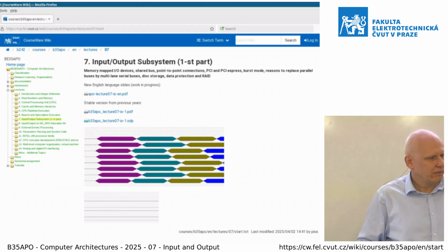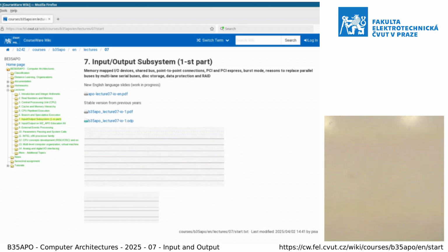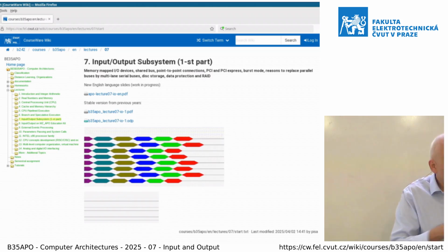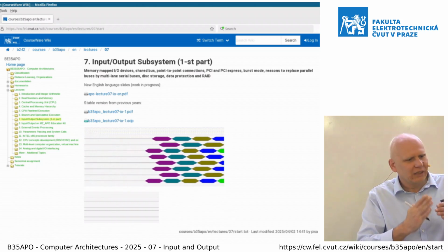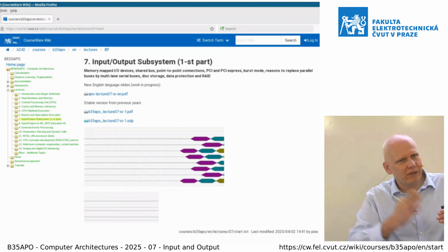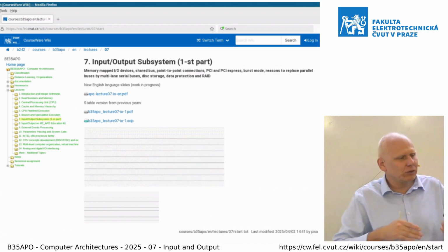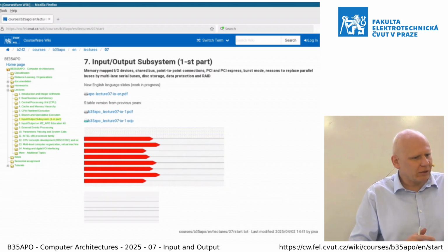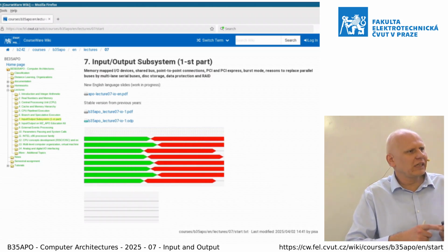That is why, in a parallel bus, all the traces have to have the same length. In this case it is not necessary. In the case of a parallel bus, yes, because you need a match between the clock signal and the data, and the data has to provide the word in the sequence at a single time. But when you switch to serial links, it is no problem, because for each lane you reconstruct the clock signal separately.